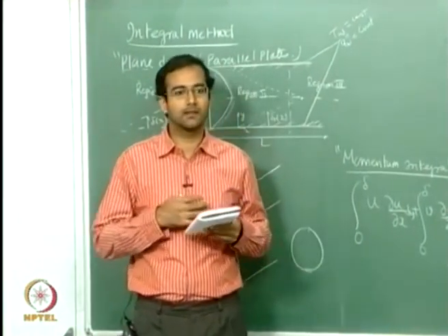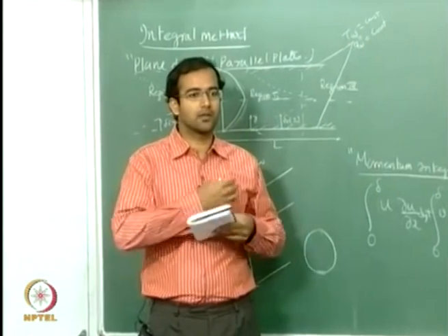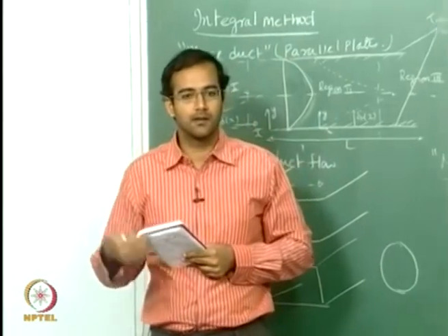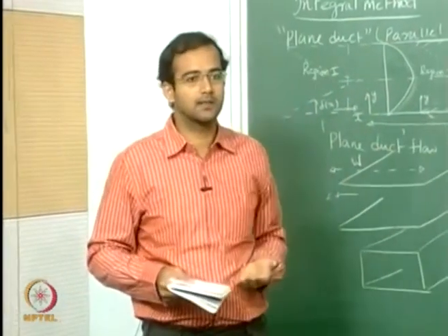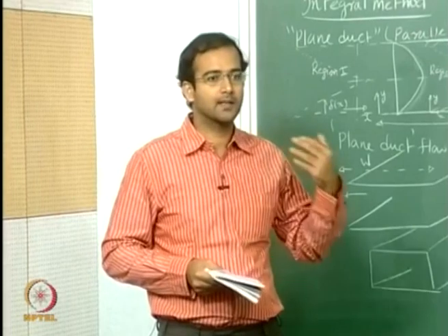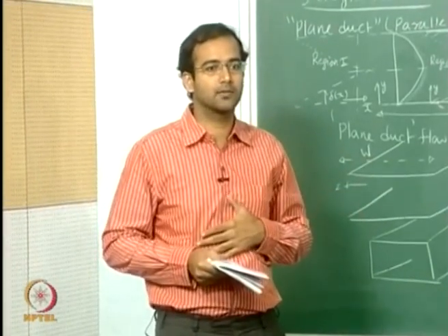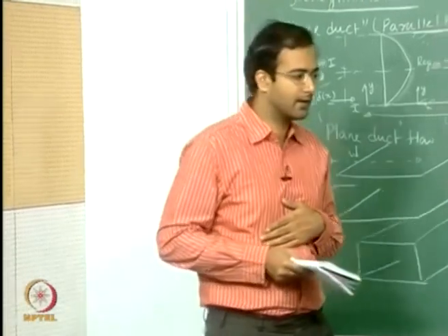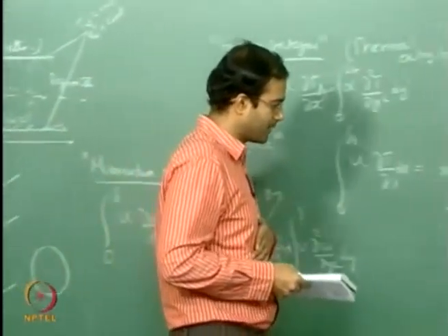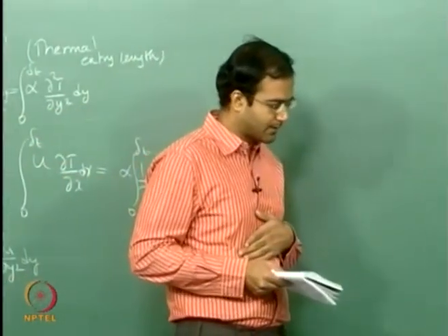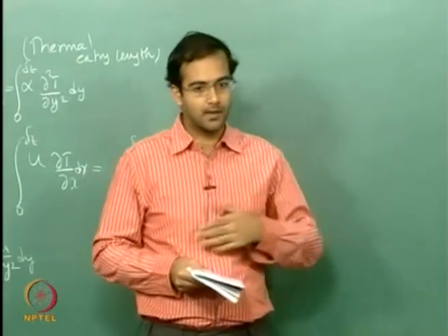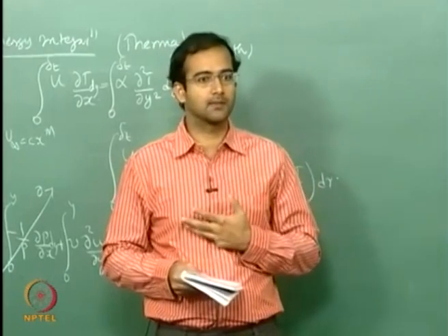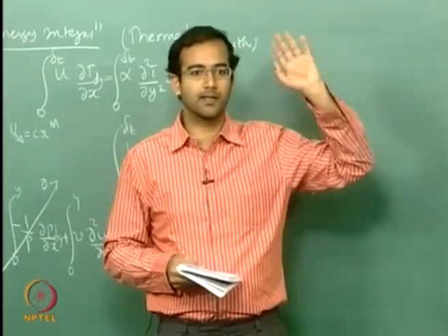It is not as wide as in external flows, where you used it for almost all the problems where you had a similarity solution. You replace that with an approximate solution, and in fact even more than that for cases where you had an unheated starting length, for example. There you cannot use the solution from similarity variables. And again, the cases you talked about with the pressure gradient were much simpler, and also the case where you had a non-uniform wall temperature or wall heat flux, so you had a linear variation or some other variation, any variation.